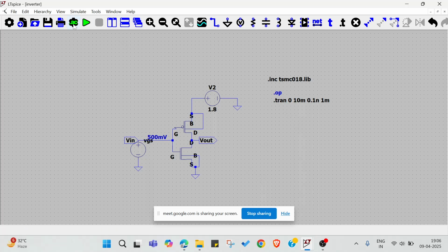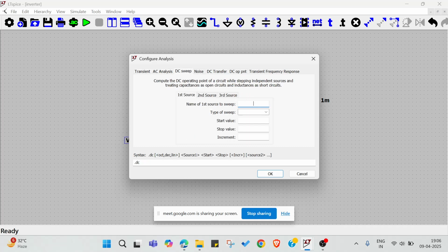Basically, what I do is I choose analysis, DC sweep, and name it VGS.